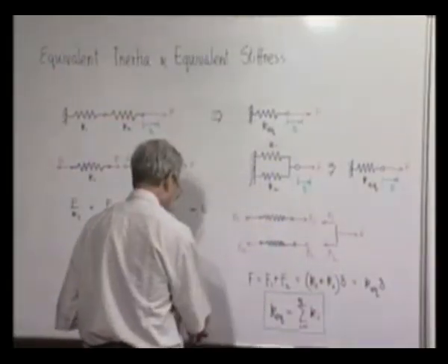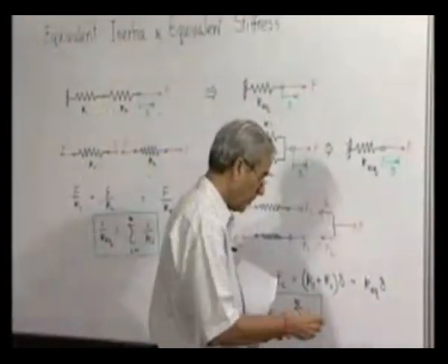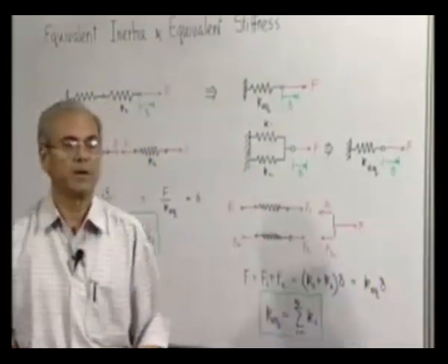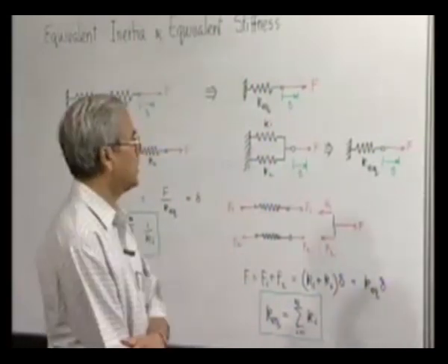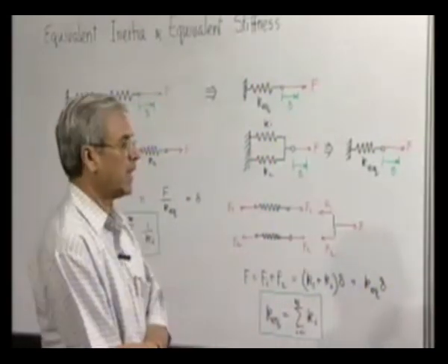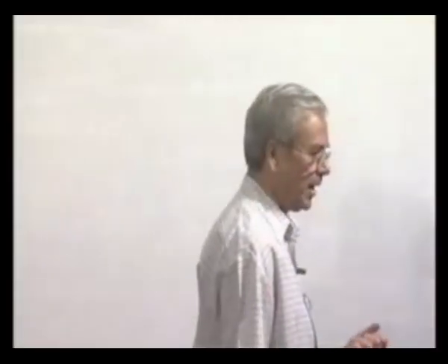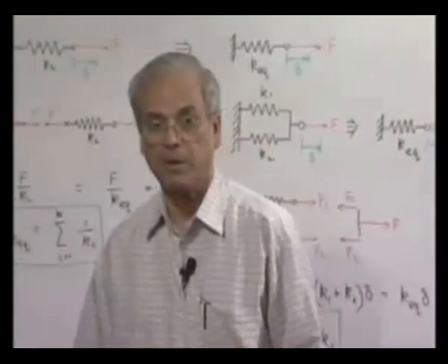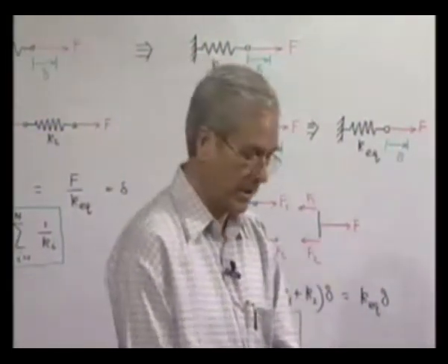Now, this energy technique which we have been discussing can also be used to solve certain other types of situations which cannot be handled by the simple Newtonian approach. One such example, which is perhaps appropriate to discuss at this juncture, is if a system has heavy springs and it is desired that the mass of the spring is also considered, at least approximately. So, how can we find out the natural frequency of such a system?